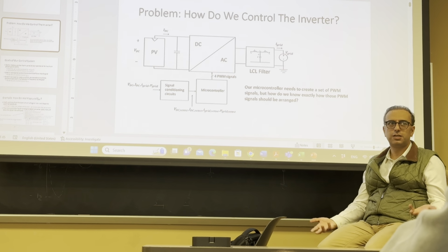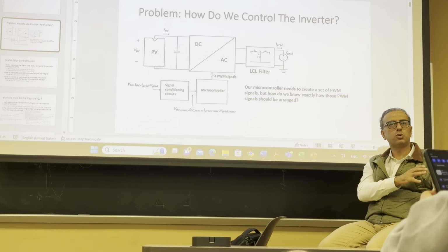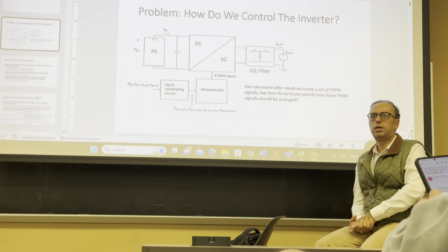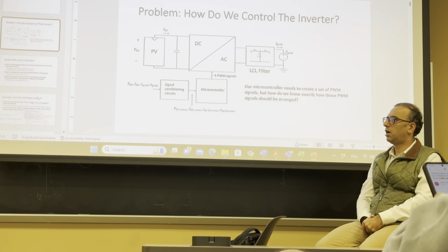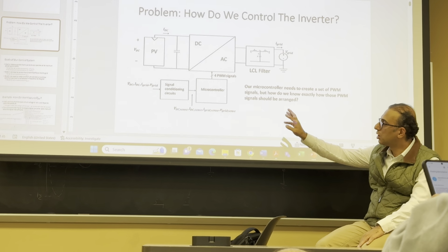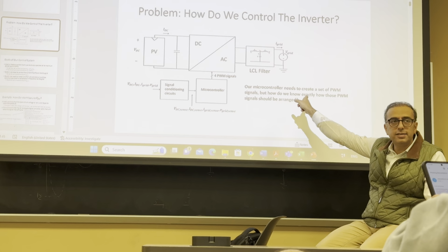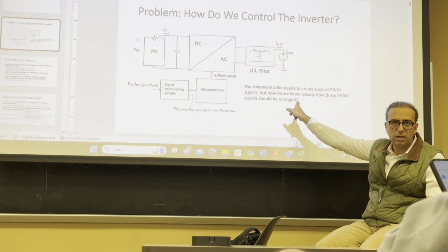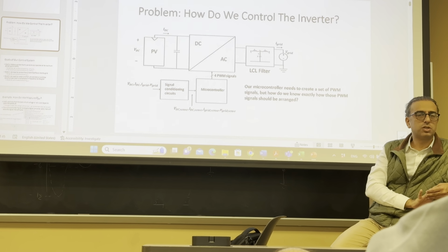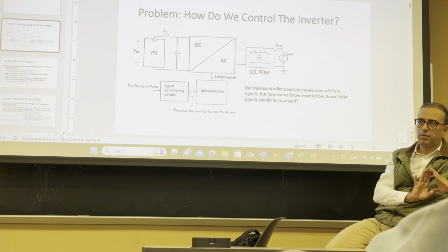I don't know if you have tested it or not, but we showed that by splitting into two first order systems, meaning having the current loop and the voltage loop, we get a faster and better quality waveform in the output. So in other words, you not only need the DC link voltage measurement, but also AC side current measurement. These are absolute musts in your system unless you're bringing more intelligence to the system, which we are not talking about now.